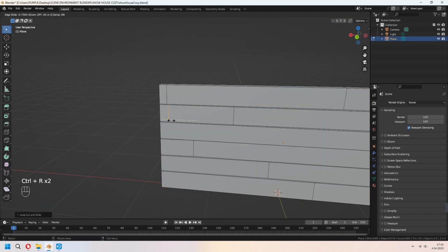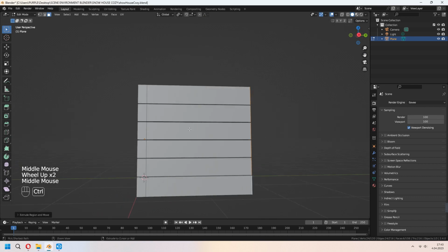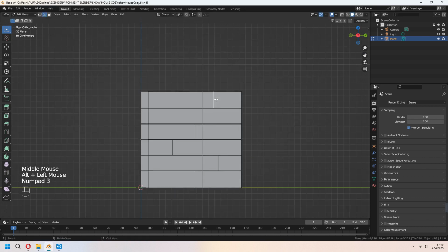For the side walls, you can add some loop cuts near it. Choose your faces and E to extrude in the Y-axis. You can make the same thing for this and add some loop cuts, with the proportional edit, G to move your some edges.